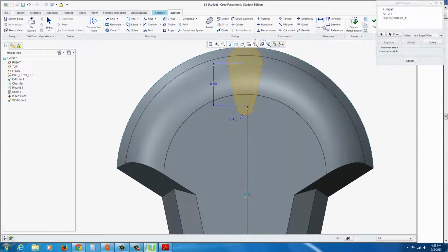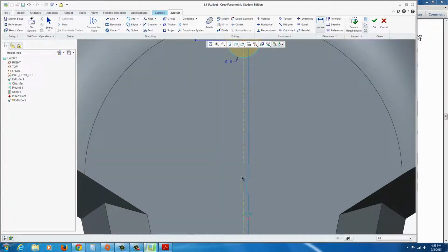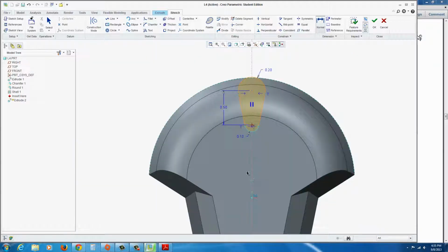And from here we could go to the Dimension tool, select the bottom center point to this center point here. We could get to it, or select the outer edge, that's fine too. That middle click between the two, and that's 0.7.